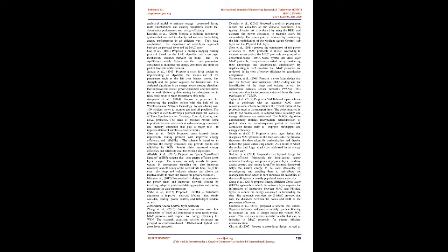Anupama et al., 2014, propose a procedure for monitoring the pipeline system with the help of wireless sensor network technology by considering over 100 wireless nodes to monitor gas and oil pipelines. The procedure is used to develop a protocol stack that consists of time synchronization, topology control, routing, and MAC protocols. The stack of protocols reveals some important characteristics such as reduced energy consumed and memory utilization that play a major role in implementation of wireless sensor networks.